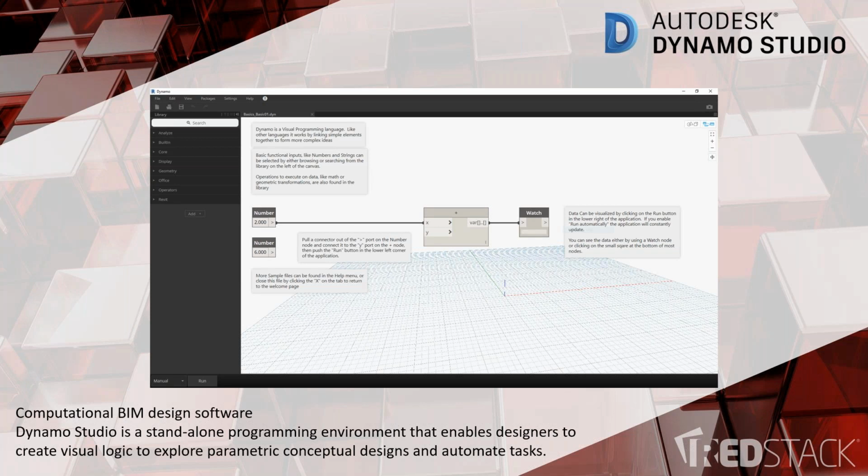So if you're doing something like a portal frame, if you've been following my LinkedIn tutorials or even my YouTube videos, I do talk about using Dynamo to build up a portal frame inside Advanced Steel, which we could adapt for Revit as well. You can use numerical inputs to adjust the length of the warehouse or the portal frame, plus the wall height, plus the roof height, and whatever else is adjustable, and then the software will automatically go through and create the models for you.